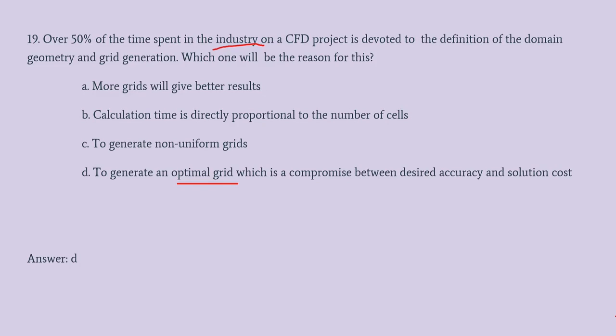So that's why the term optimal grid comes. Suppose we are reducing the del x del y to lower values, then the number of grid elements will be much higher. And if you keep on increasing the number of cells, it is not likely that you will keep on getting good results. Like the catching fish example, beyond some level, it won't help, because once that particular variation can be captured by your del x and del y, further decreasing del x and del y won't be helping because you will be getting similar results.